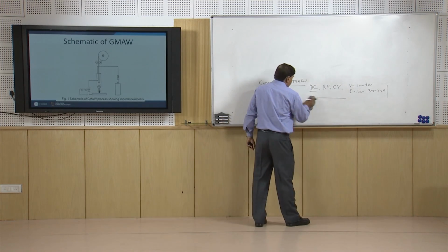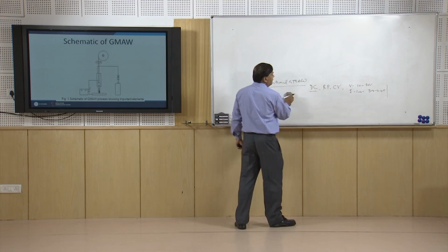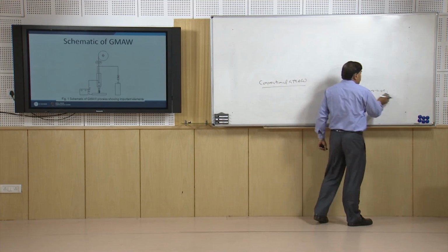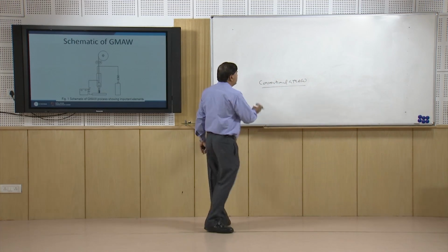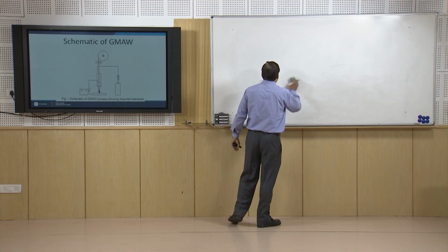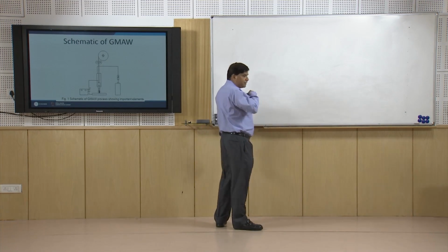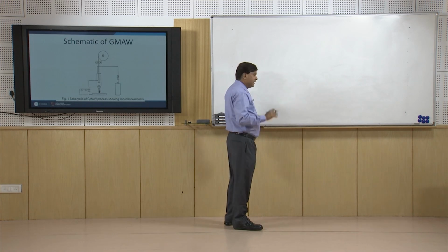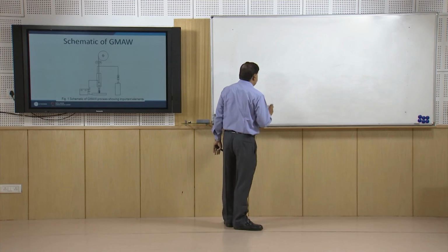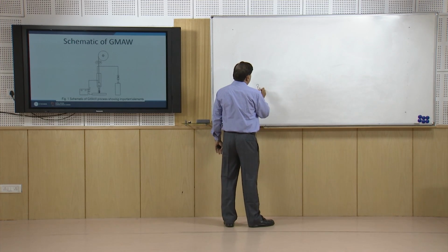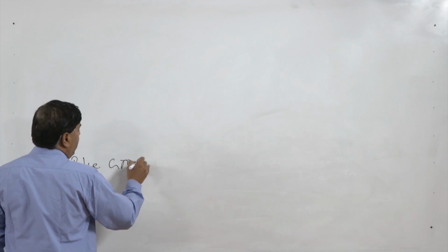But in some cases, when we intentionally want that heat delivered to the workpiece is limited in order to avoid its related adverse effects, then the process is modified intentionally, and in that case we do not deliver the constant current like DC, but the current magnitude is controlled in a particular manner, and for that we use the pulse GMAW.